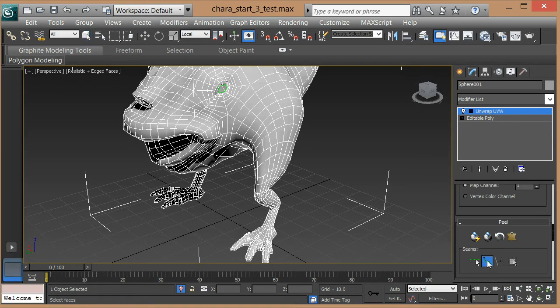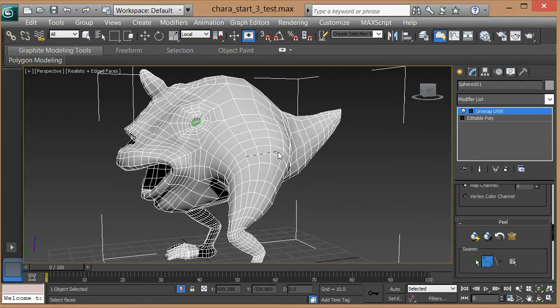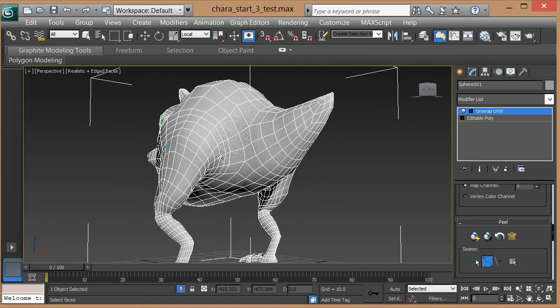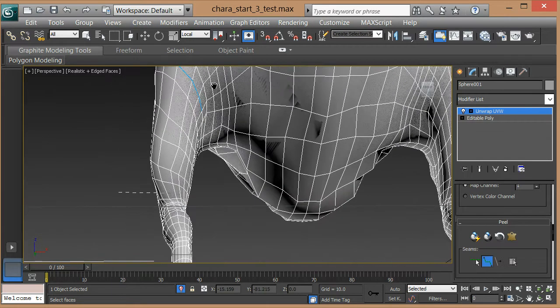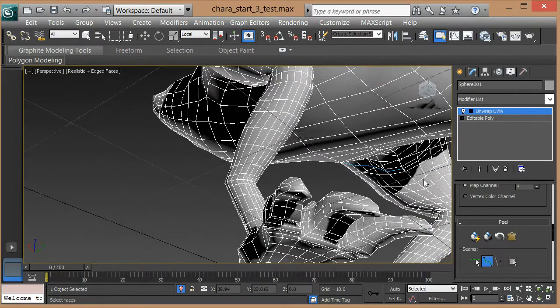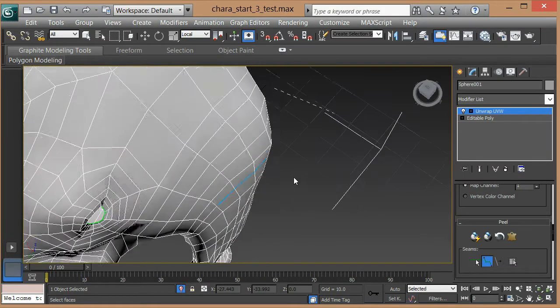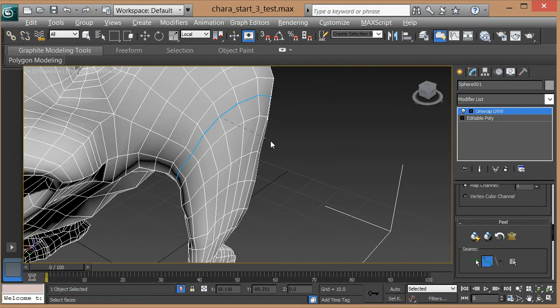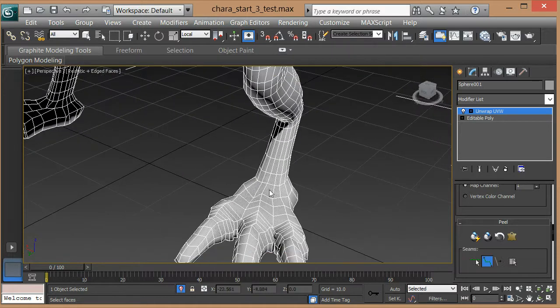What I'll do is click point to point. Then I click over here. Now I'm defining my own UV edges with the point to point tool. Eventually those edges are going to be new UV seam lines. There we go. You can right click to exit that tool.